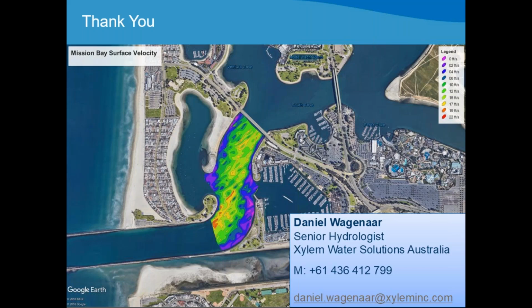From the research that was done to date, almost all the instruments, including the StreamPro, showed a bigger influence on the velocity patterns around the instrument if it was implemented on its own, meaning it wasn't mounted on a board, it was mounted on a post where the instrument was placed in the water directly without using a trimaran boat or hydroboard or what type of float. So that was the first obvious thing that came out of the research, that the instrument on its own seems to generate or impact the flow disturbance around the instrument more.